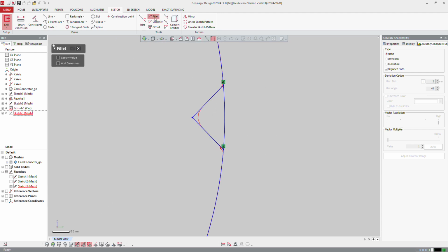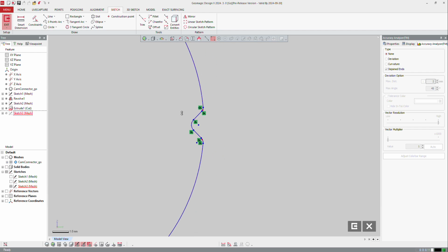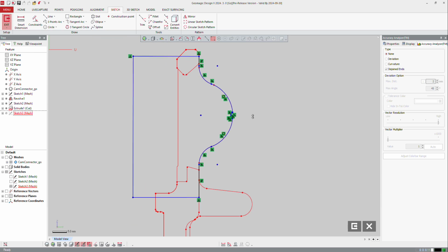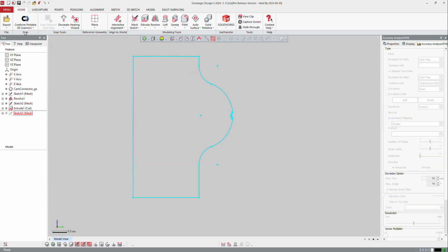Of course, I can also create the fillet between here and there. And of course, at the end here, if I trim, same thing. So power trim, I will remove that. I can make a fillet from here to there, a small fillet here to there. You can do that or specify your value if you prefer. Okay, I got the complete definition and I will exit.